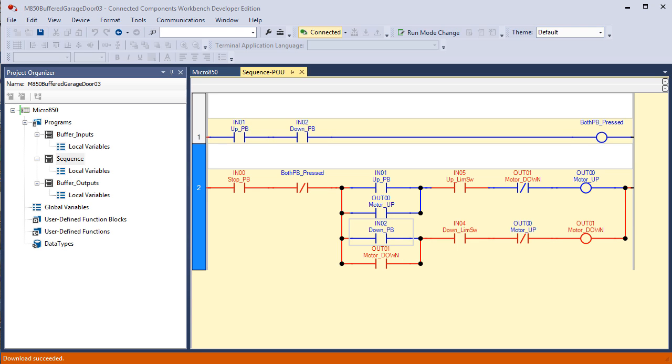Now remember that I said, pertaining to the previous rung where everything was in one rung, that as soon as we let go of both buttons, it stopped because there was nothing there to seal it in. Where would we put something to seal in this condition? I'm going to go offline and make the edits that I suggested, and then we'll be back.